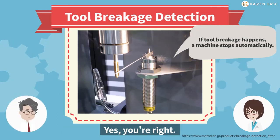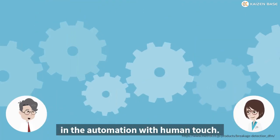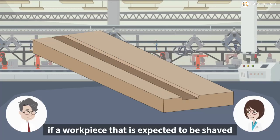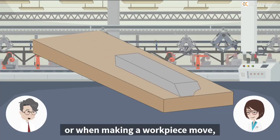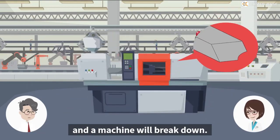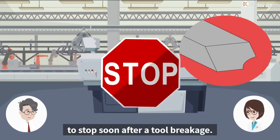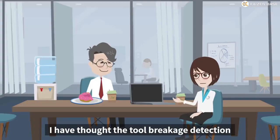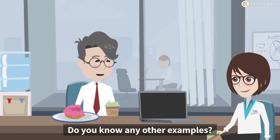Yes, you're right. The tool breakage detection is a popular example in the automation with human touch. In equipment of a machining process, if a workpiece that is expected to be shaved is not shaved, it will become a defect, or when making a workpiece move, the tool will interfere with it, and a machine will break down. As that will not happen, a machine incorporates the structure to stop soon after a tool breakage. I have thought that tool breakage detection was an easy example to understand. Do you know any other examples?